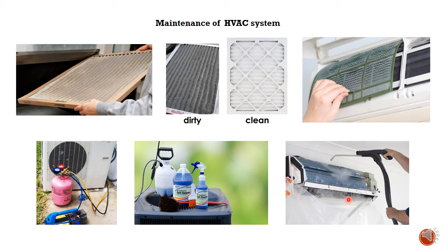And this one is chemical maintenance, using chemicals to clean all the dust and rust, for example, in the air conditioning system, in your split unit system. Just imagine if this one is not clean, then the blown air will carry the dust particles together with it, not to mention the bacteria or any unwanted particles embedded in this dirty filter, which will be carried into the space also.